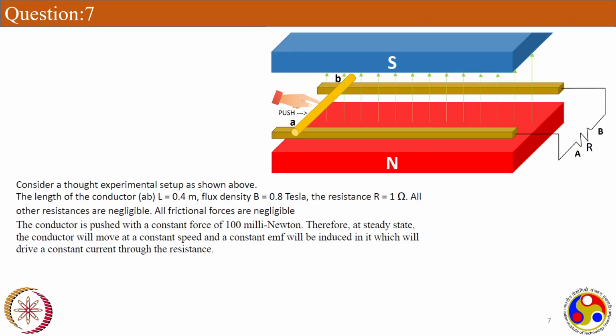Okay. Now you remember the second week's discussion where we were discussing Fleming's right hand rule and left hand rule. Using the right hand rule, we will decide the polarity and magnitude of the voltage, and the left hand rule we will use to determine the polarity and magnitude of the force, right? So the left hand rule is like a motoring operation, you get some motoring motion, and the right hand rule is a generating operation because it generates electric voltage between any two points.